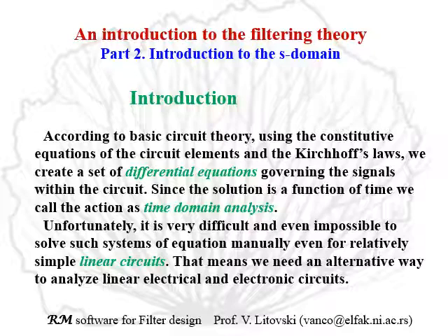According to basic circuit theory, using the constitutive equations of the circuit elements and the Kirchhoff's laws, we create a set of differential equations governing the signals within the circuit. Since the solution of these differential equations is a function of time, we call the action time domain analysis.